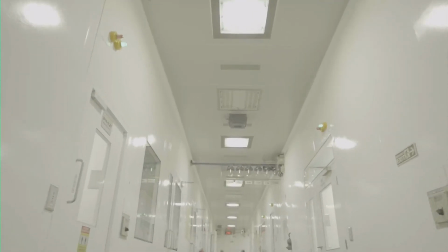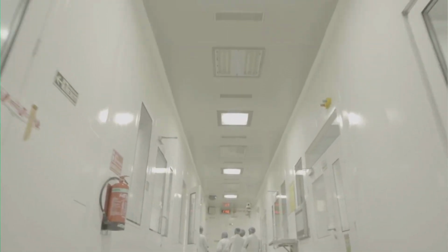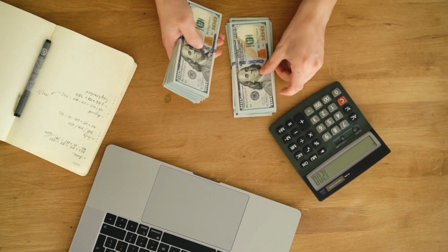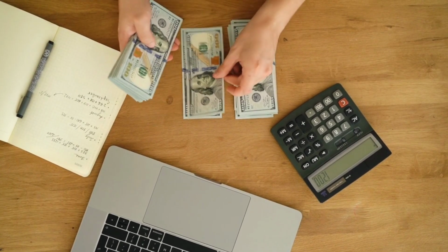Based on the URS, the clean room design is developed through aseptic and non-aseptic parameters. Aseptic parameters, for example, temperature, humidity, process condition, clean room recovery time, equipment, material, and personnel flow. Non-aseptic parameters: project budget, timeline, and management of technical staff, etc. After getting approval of the user requirement specification, factory acceptance test and site acceptance test should be evaluated. Only then does installation qualification start.